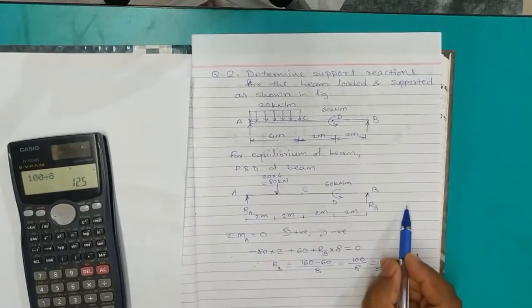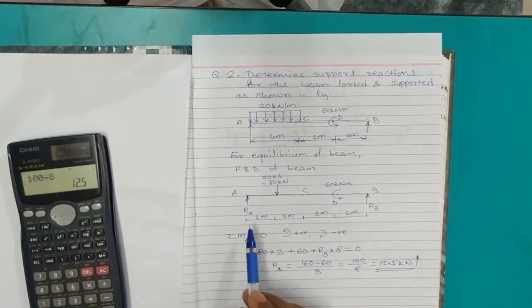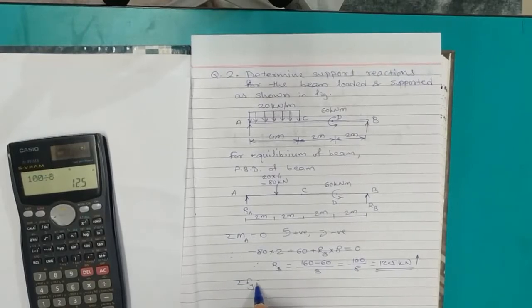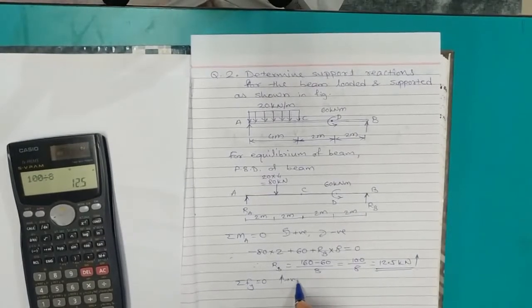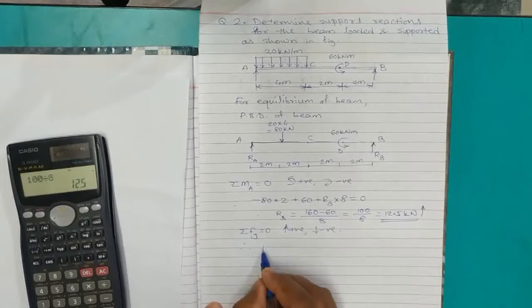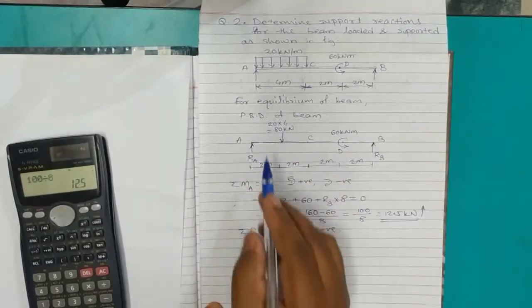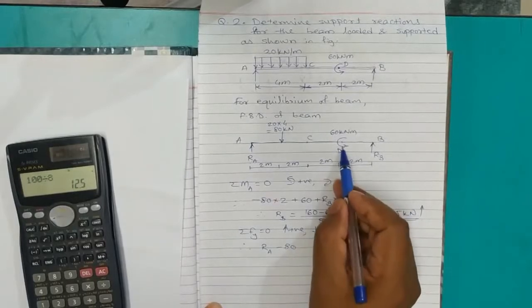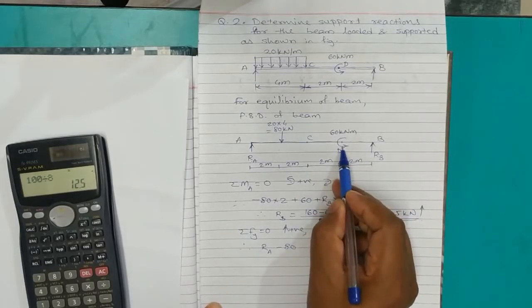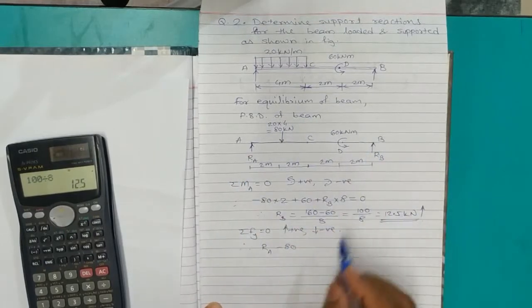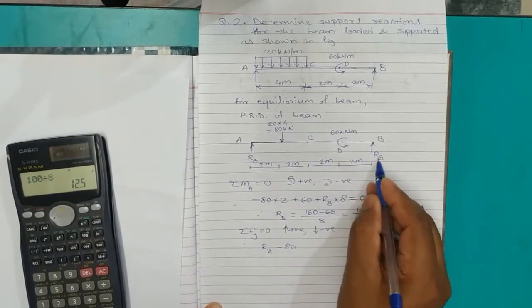There are no horizontal forces existing in the system, only vertical forces. So RA should be calculated by using summation Fy equals 0, upward positive, downward negative. Using this condition, we have unknown RA taken in the upward direction, so positive, minus 80. We don't have to add or subtract this moment now. We just use the vertical components existing in the system,